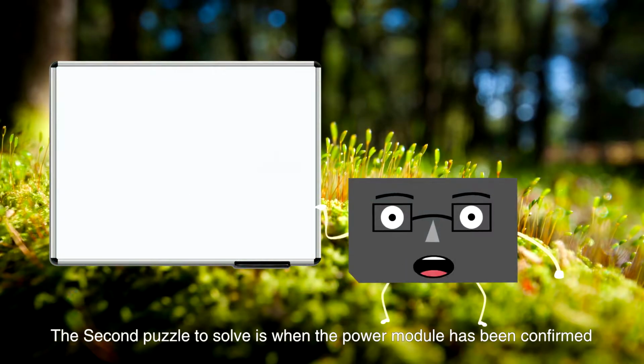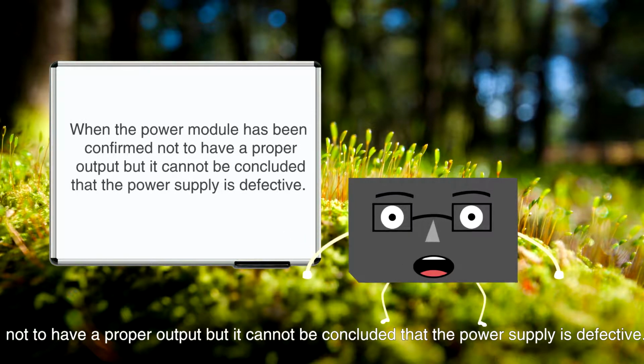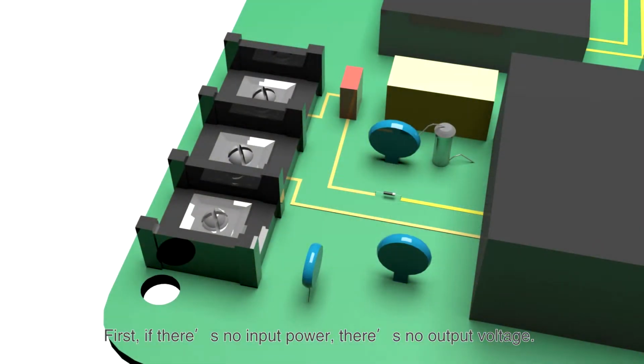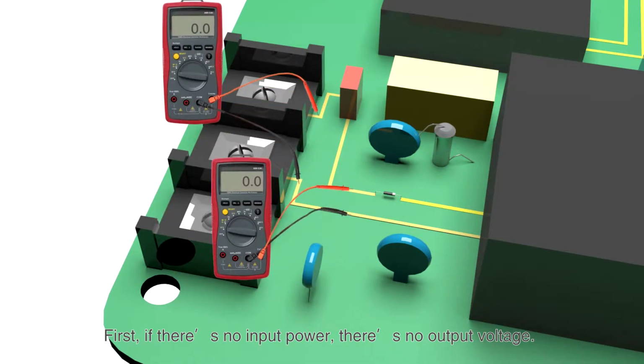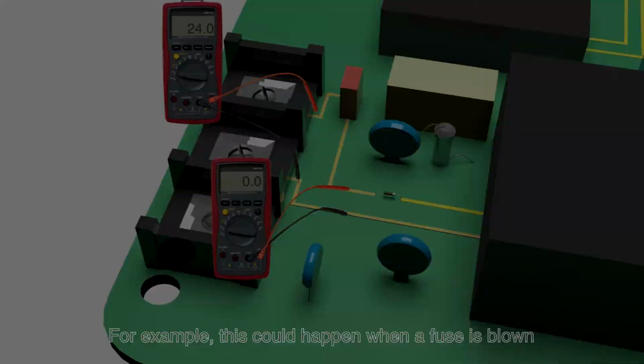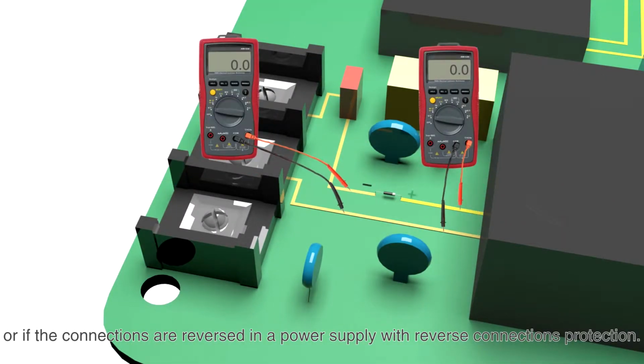The second puzzle to solve is when the power module has been confirmed not to have a proper output, but it cannot be concluded that the power supply itself is defective. There are many reasons for this. First, if there is no input power, there is no output voltage. For example, this could happen when a fuse is blown, or if the connections are reversed in a power supply with reverse connections protection.